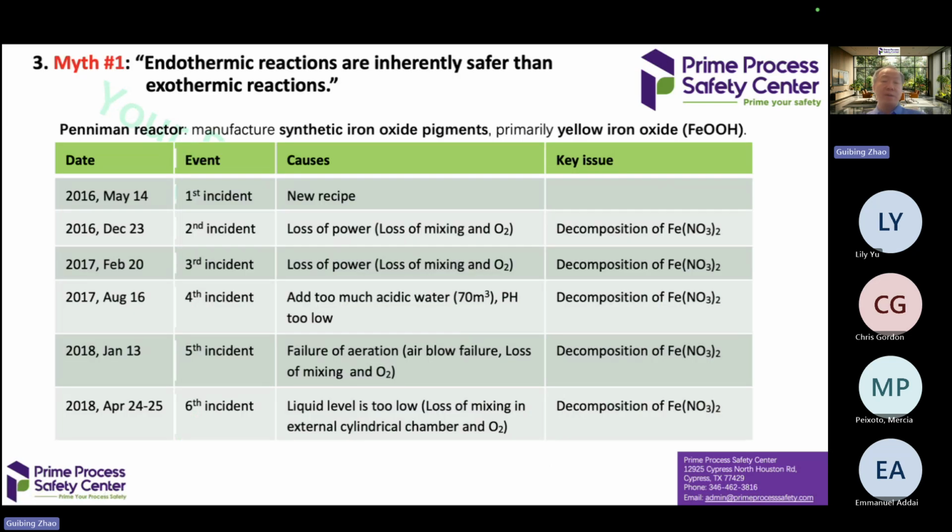The first myth: endothermic reactions are inherently safer than exothermic reactions. This is really not the case, especially for some reactions, for example with gas generation. Be careful when we talk about endothermic reactions. For many of them, yes, an endothermic reaction is much safer than an exothermic reaction if there's no gas generation. However, if there's gas generation, this can be a total turnaround.